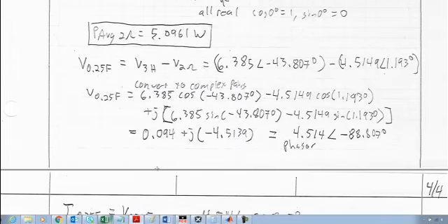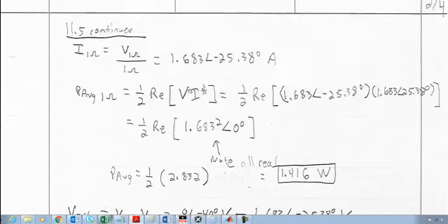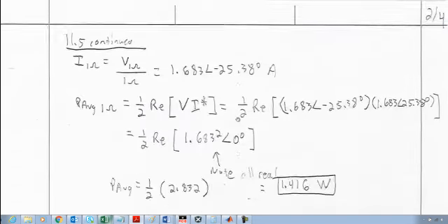Now, moving on to our last component, the capacitor here, you can figure out that the capacitor voltage is going to equal the voltage across the 3 Henry inductor minus the voltage that's dropped across the 2 ohm resistor. Let's review why. If we go back to our schematic, which now we've gone through several pages of calculations, if you know the voltage here, and then you know the voltage that's dropped there, you can take this node voltage, which is going to be the same as the voltage across the inductor, subtract off the voltage you just calculated is dropped across that 2 ohm resistor. That's going to tell you how much voltage is dropped across the capacitor. And so we're just going to subtract those on down.